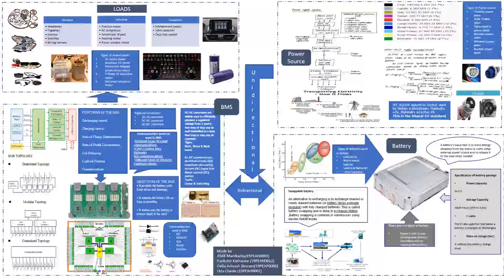And from the power plant, we produce 11 kilovolts to 30 kilovolts from the generator of the turbine. Then it is fed to a step up transformer, which steps up the voltage at the power plant itself, to carry the current in fewer cables.